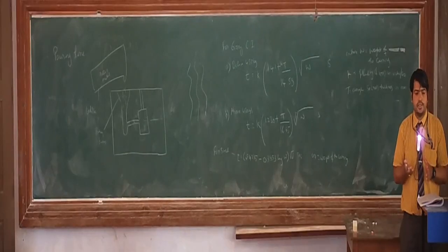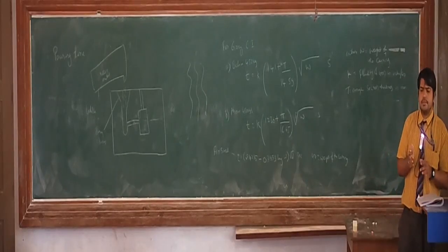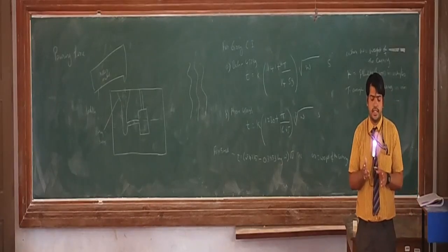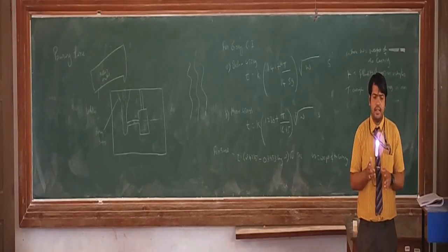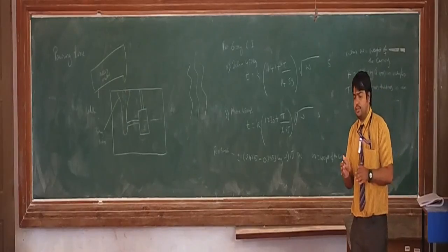This is the reason why risers are generally not provided in simple castings of cast iron, or the risers used have smaller dimensions compared to steel castings. In extreme cases, a steel casting has a riser whose width is approximately equal to the width of the casting. So this is the thing with different metals.